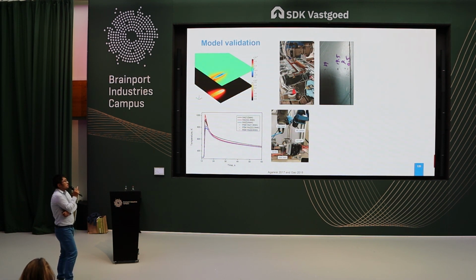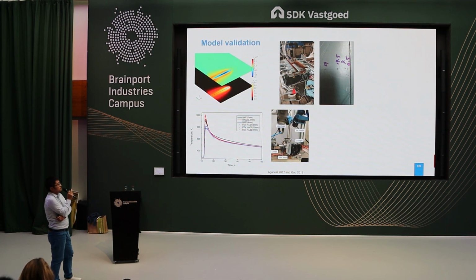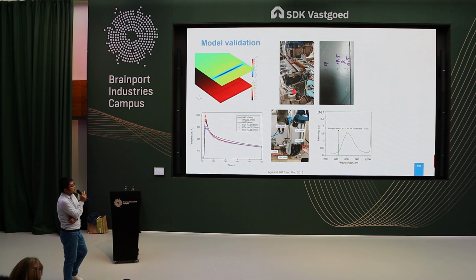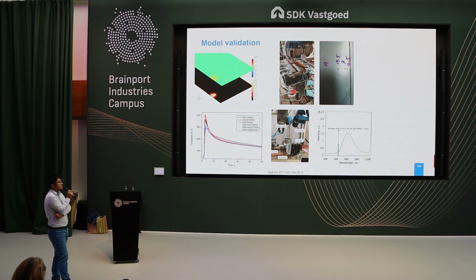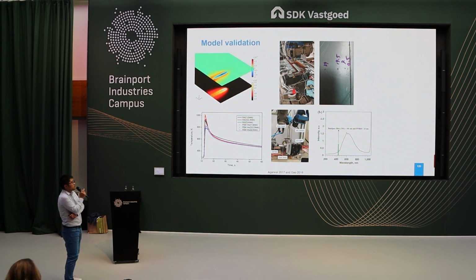So our solution is to put a bandpass filter in front of these two cameras. You can see this is a typical wavelength of the laser plume, and then we select 450 nm for the bandpass filter, which means that only the blue light will go into the camera. But this also introduces another problem: only light within this full width at half maximum will go to the camera. Therefore, we need to put two additional blue LEDs for illumination.